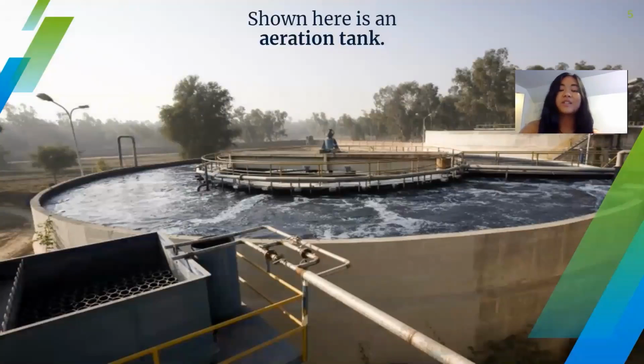All activated sludge systems contain two main components. The first is an aeration tank that carries out the biological treatment process, and the second is a clarifier tank that settles sludge and separates the treated water. Aeration tanks must be large in order to treat large volumes of wastewater, and they also require large areas of land needed for their operation. Other essential equipment include pumps, flow measurement devices, and mixers and blowers that provide aeration.